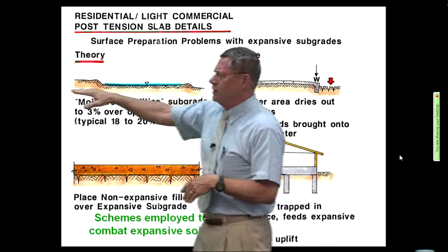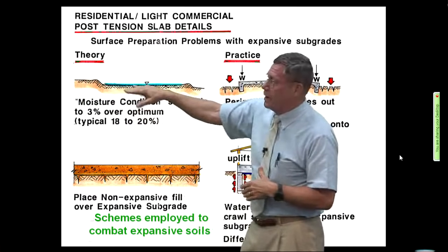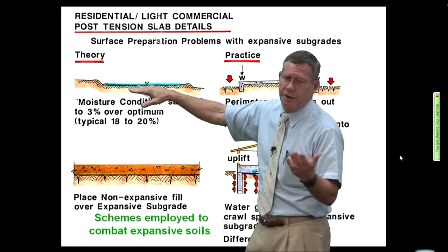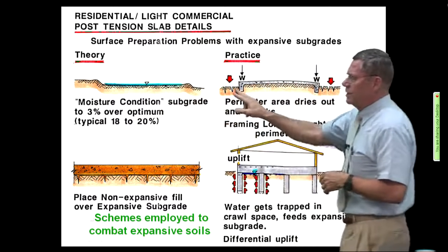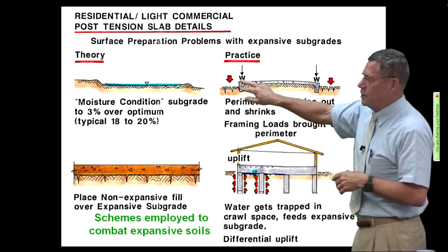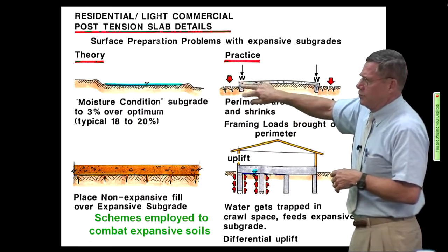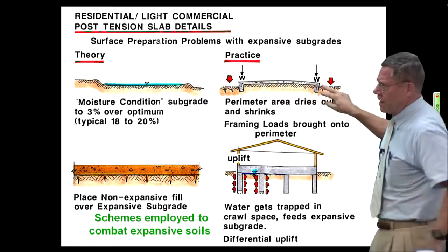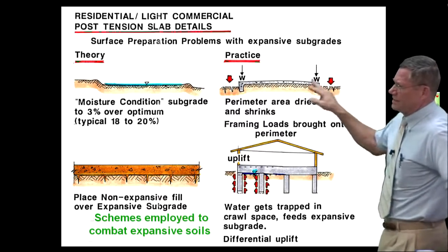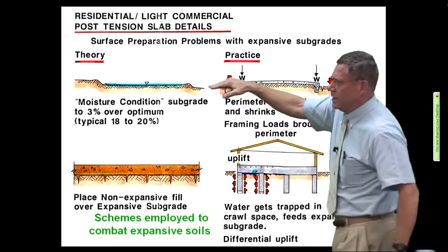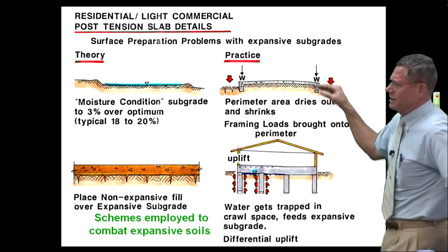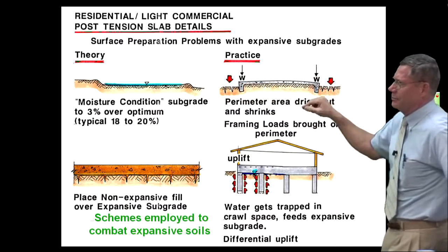What you don't want to do is go from a dry to a wet. The wetter it is when you build it, the better you're going to be. You're going to get less heave. Now, another thing was, put post-tension or put cutoff walls on the slab on grade. This turned out to be more problematic because you get more uplift on these when you do get water over here next to the structure, and it tends to edge curl and lift up more easily.